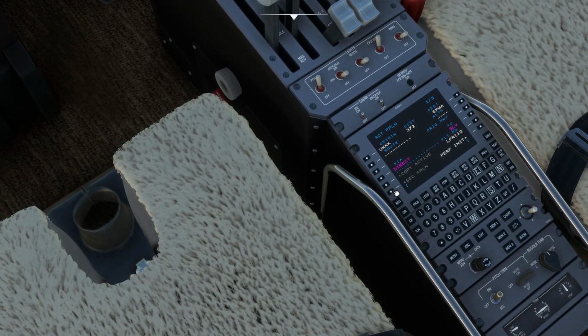Going back to FMC, so the flight plan. Again we're departing Zhuliany, so we click departure arrival. We will be departing runway 8 and we are flying towards SLV point. We just need to check on the charts which number is which. SLV is 2K, departing runway 8. 2K. Right, there's no transitions, and we execute.